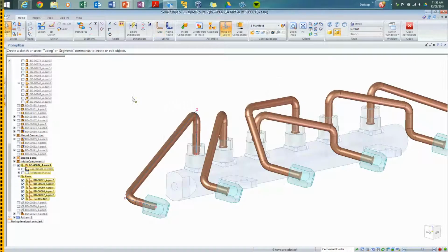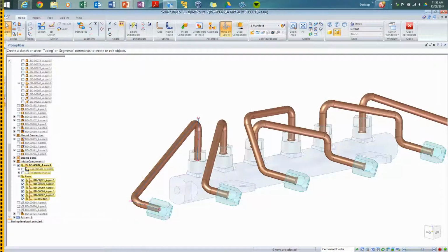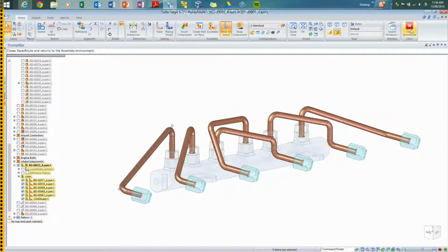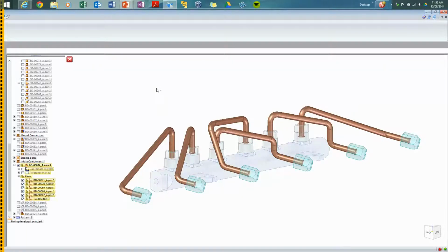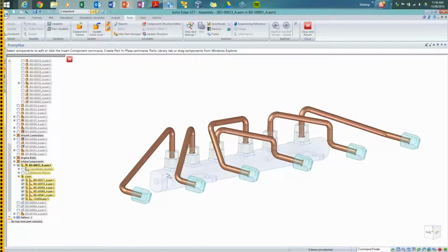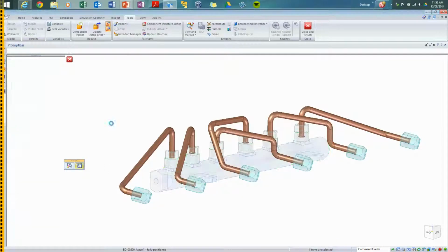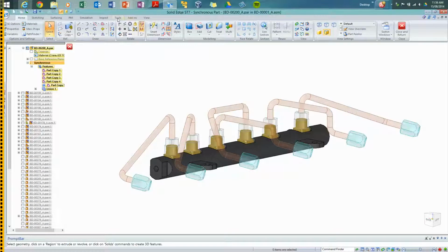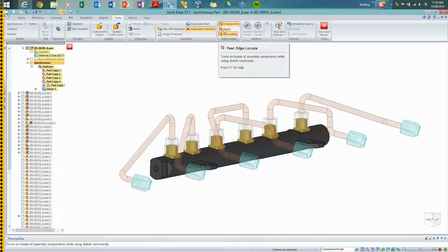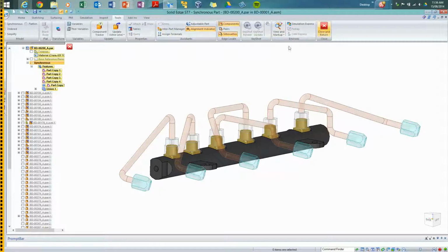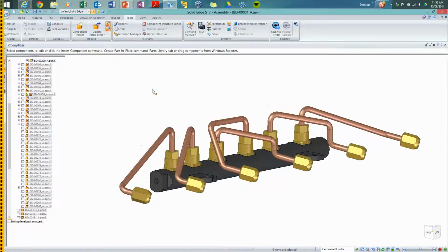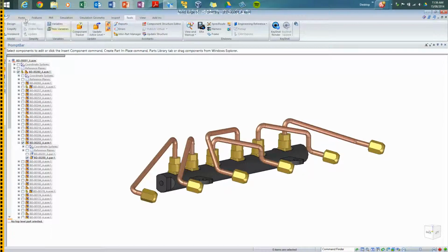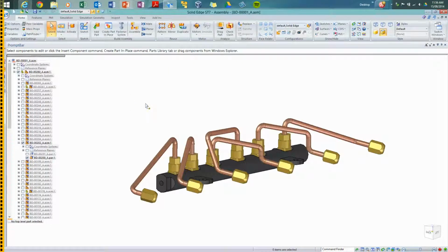I don't need another one, but you can see it says created that tube and added it to the assembly of tubes. So just be careful. It's not the same as the peer geometry tool, which is still available. So if we go into the part file, if I go to tools, then peers is not on. Okay, so that hasn't changed. The function of that tool hasn't changed, but the ability to use things like XpresRoute to create or pick up geometry from components outside of the assembly that we're in is the new tool.